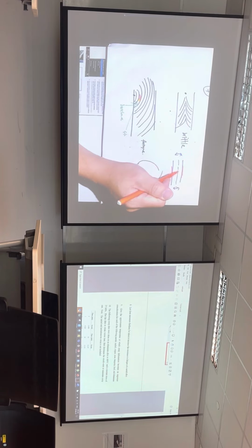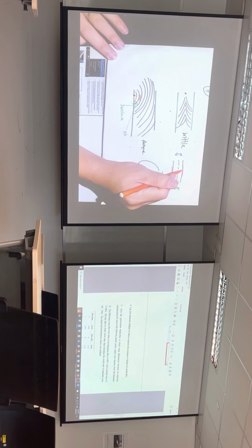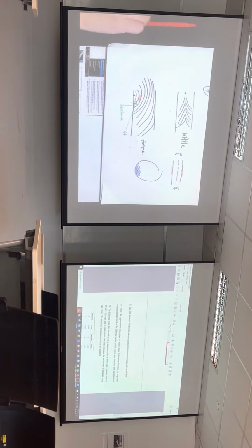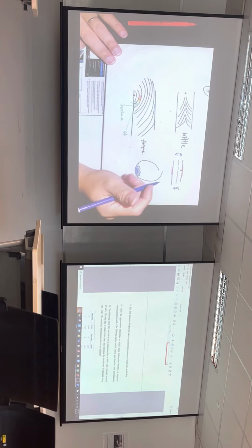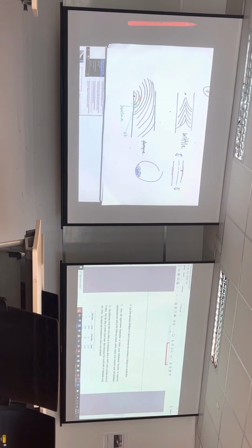Okay, so a lot of amplification is happening on the top. If I have a crack here, compression, tension, you flex up and down, right? The central axis will not have a lot. It's the outside that has a lot. So if I have a crack that's on the outside, then that becomes an initiation for my fatigue failure, right?